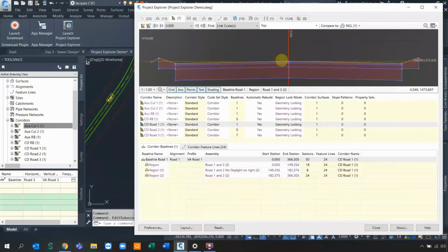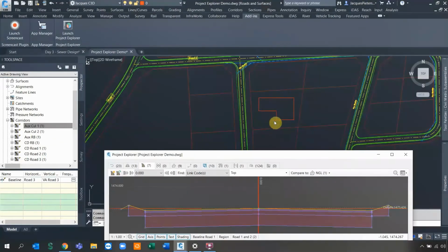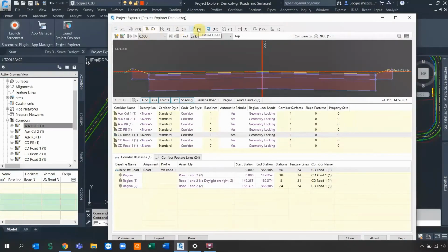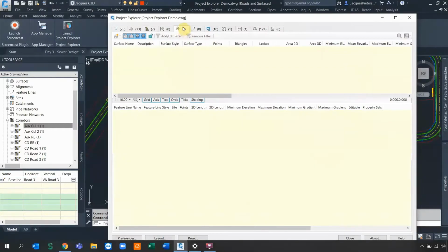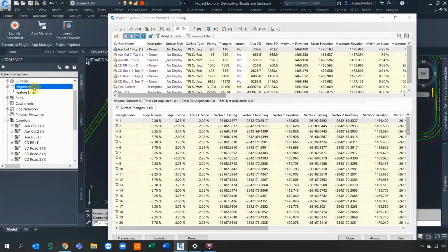So this is very unique, specifically for roads, but we're not limited to just roads. What, say, for example, do I have with feature lines and surfaces? So we have an option where we can create a feature line from objects, as well as you have the option to define surfaces. So with surfaces, there's one nice tool that I like about this. Instead of going to the surface, you can simply go pick up all of your surfaces from this directory. Instead of going to surfaces,